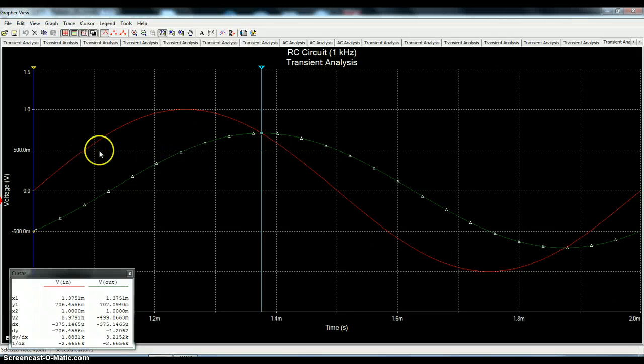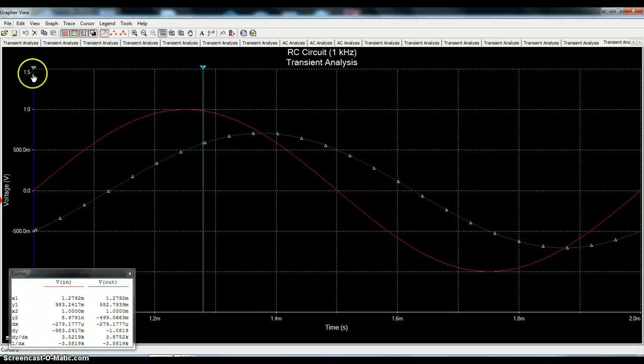I'll go ahead and use this particular display. To get even better accuracy, we could actually show this only over a quarter cycle and do even better, but I think this will be good enough for the purpose intended. Now cursor 1 is already set at the beginning point, so what I want to do is to find a 0. Now I'm moving this back to the left of the 0 crossing to make a point.